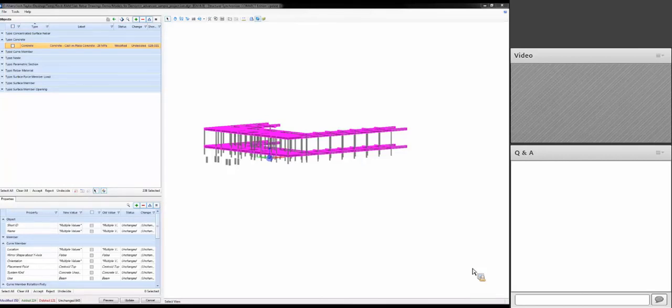I would say that it depends on what type of material it is. For a concrete model, and I would say for a flat slab structure in general, there's really no problem going either way. When you have a model that's steel framed, now you have to worry a little bit more about the connectivity of the individual elements, the beams to the columns, the beams to the beams,